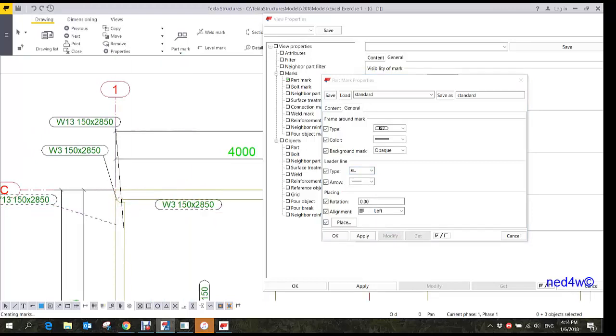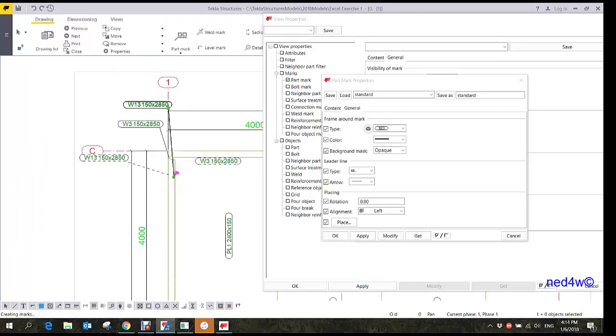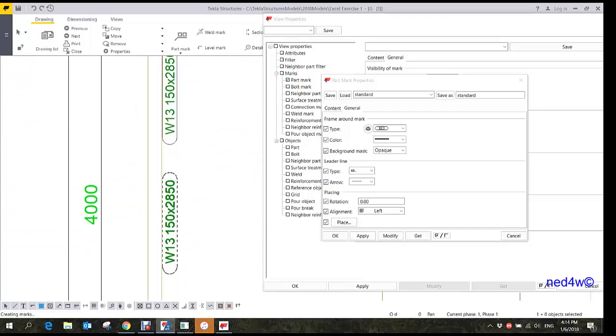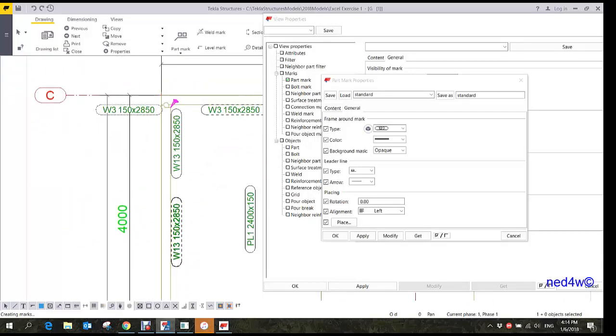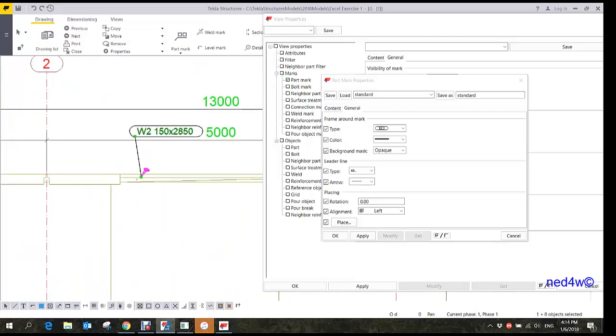You can still force it if you like. But if you're okay with this one, then do it. And then here, let's say modify, so I can force it this way. So here, because there are 2 walls, one below and one above, I can simply delete one of these. Alright? So this one is okay.